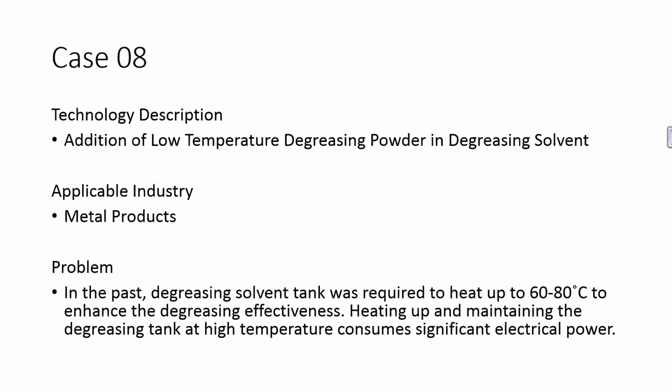Case number 8. It is also from metal products. Addition of low temperature degreasing powder in degreasing solvent. The problem is in the past, the degreasing solvent tank was required to heat up to 60 to 80 degrees Celsius to enhance the degreasing efficiency.